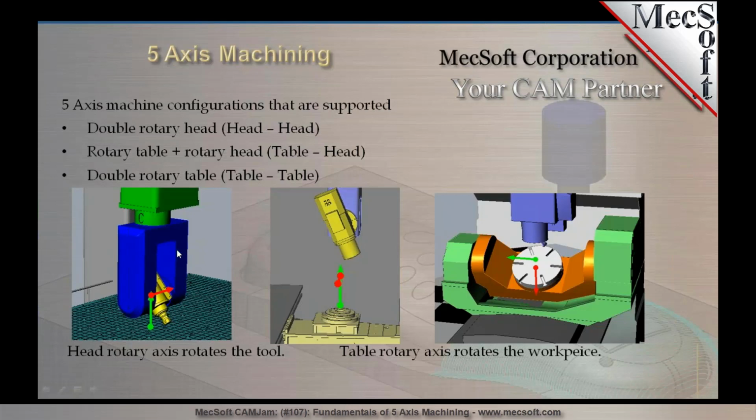That is when we say the machine tool, all the axes are zeroed out, then we look at the machine tool configuration and say about which global coordinate axis is the head rotating. What is the primary axis rotation about? The global Z, which is typically called the C axis. And then, depending on your machine, it's either about the global Y or the global X. So that's how you define the secondary axis. So hope that makes a little bit more sense.